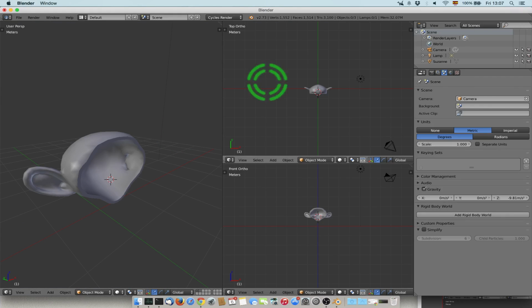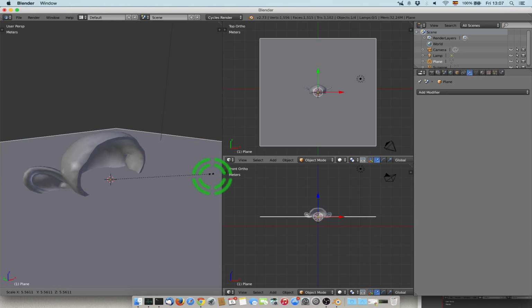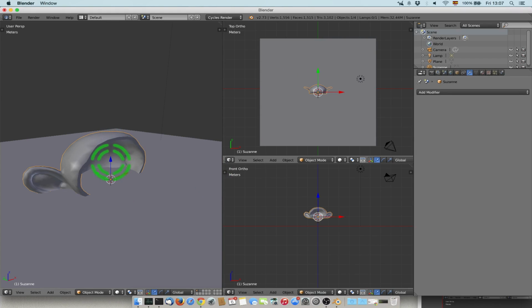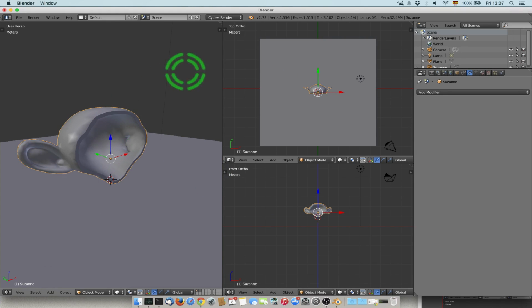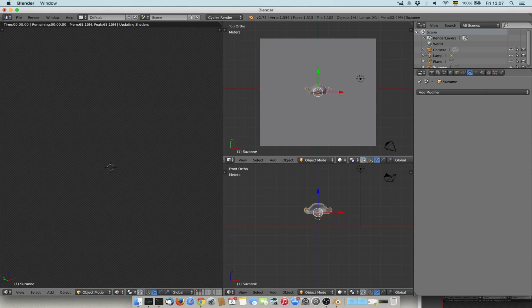These are the basic things. One thing more, for example, I will show you quickly how to do the rendering. I add a plane. I move this up. Okay. One thing that I can do now, if I put in render view, I see the render in real time. If I click on this, I can change the color, the material. So for example, that's diffuse. And now I see in real time how it works.